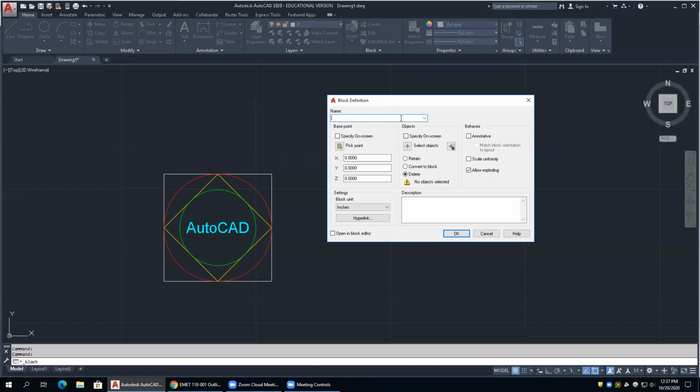So if you created a block that had more than that, or if you had a drawing file that had more than 8 characters, it wouldn't work as a block. Okay. Now you don't have that problem, but I still get occasionally, even in this newer version of AutoCAD, if I try to insert a block with a weird name, it doesn't like it. So I have to go out and rename it. I usually still keep my characters to about 8, just to be on the safe side.